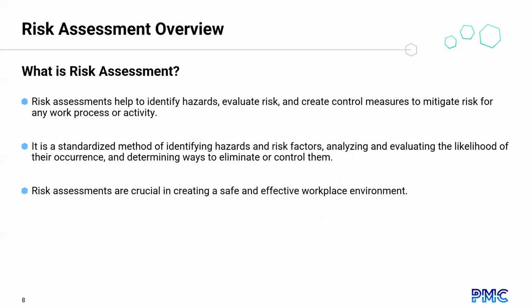And what is risk assessment? What is it for? Well, the risk assessment is a standardized document that helps us to identify hazards, risk factors, evaluate the likelihood of their occurrence, the frequency of exposure of the operator to the risk, and also to point out control measures to mitigate these risks. So the risk assessment is suitable for any type of process or activity. And in this webinar, we'll give more emphasis and we'll cover examples in the robotic cell.